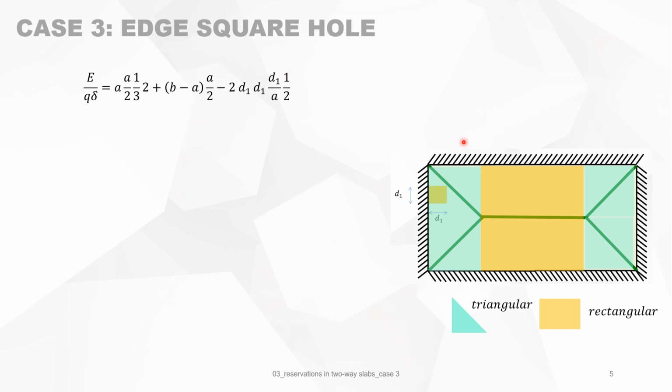and it's not cutting yield lines. Now, for this type of hole, we do the calculations of the work done by the external forces. Again, we will use the superposition of load cases. So we will consider the slab without the hole and subtract the effects of the hole.